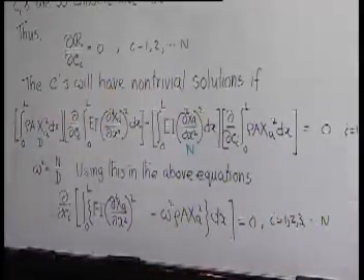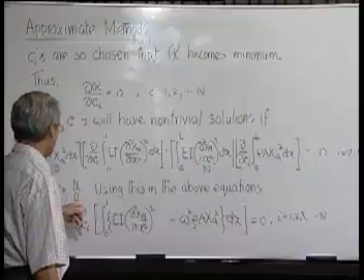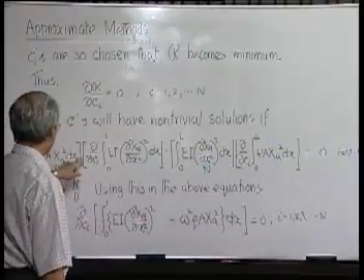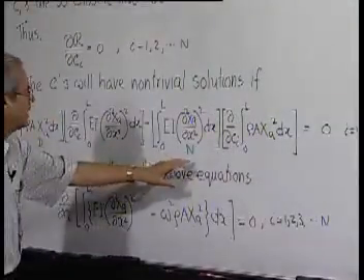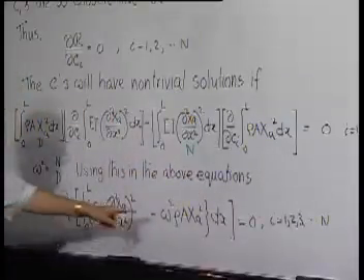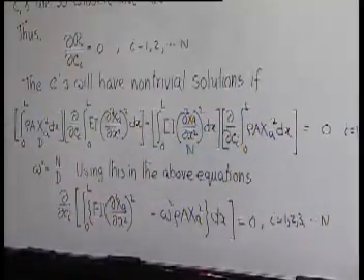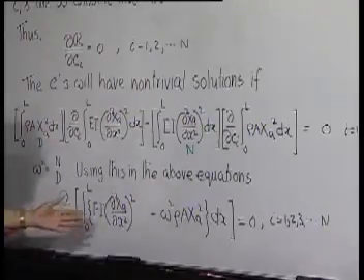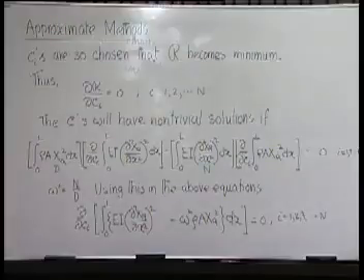so there will be now n such equations. It is very easy to see if we use this, so therefore we can always take this common, take out this. The moment we take out this, it goes below here and this becomes omega square. So it becomes omega square and then this remains. So therefore it is straightforward. So then what is done, that these n equations in Ci, C1, C2, C3 up to Cn, and these homogeneous equations can have a solution only when the determinant becomes 0.